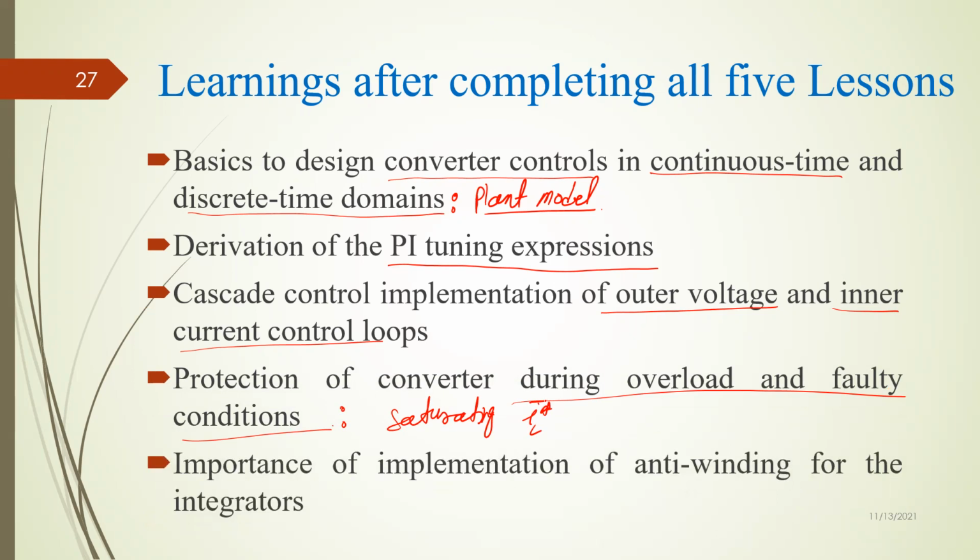And last but not the least, you know what anti-windup is and why it should be implemented. There are many ways to implement anti-windup, and what I have shown is just one very simple approach. Anti-windup is very important, especially when you have fault or overload conditions. So this is all about this video.